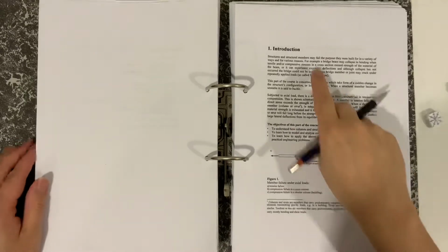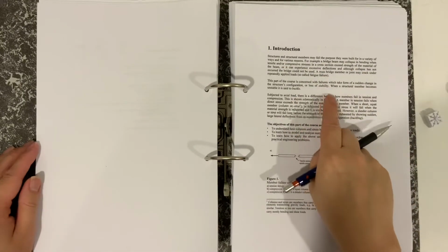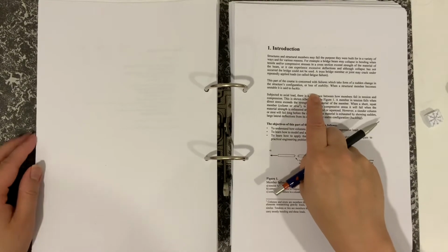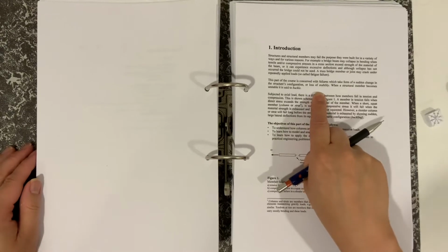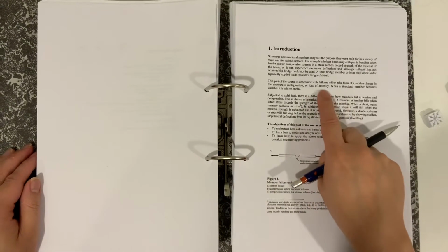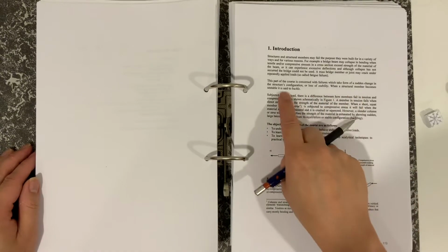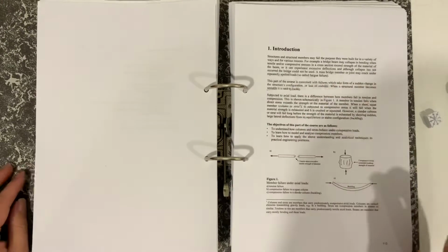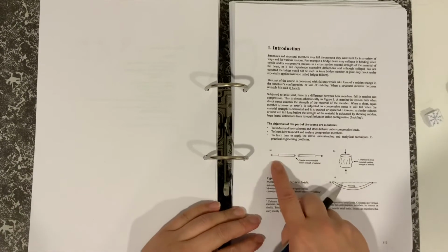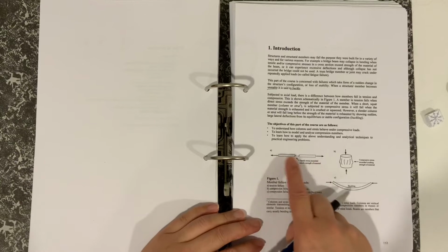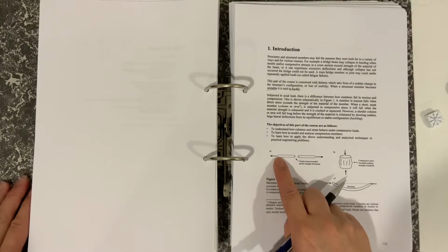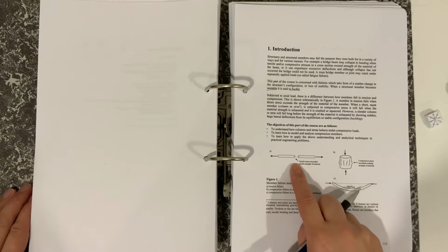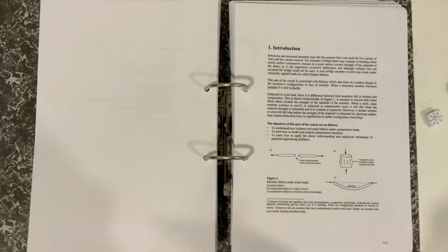So, introduction to buckling. You can read that, but I hope I've demonstrated it, and you can also get a feel for what buckling is with a simple ruler. Just apply some compression onto that ruler, and you will see that it suddenly buckles or suddenly becomes unstable. So buckling is an instability, and I've already demonstrated what happens when you reverse the direction and put it in tension. There's no instability, and if it goes in tension, it would presumably fail by the material failing. Okay.